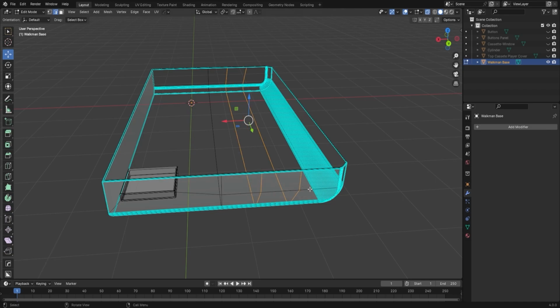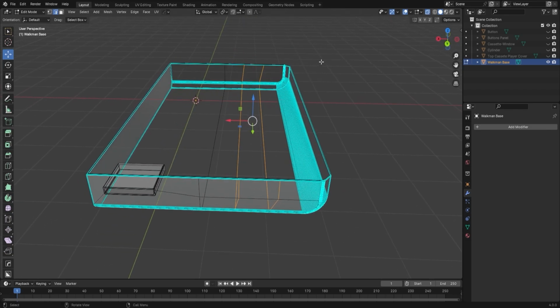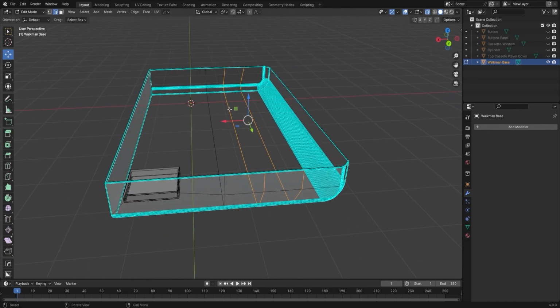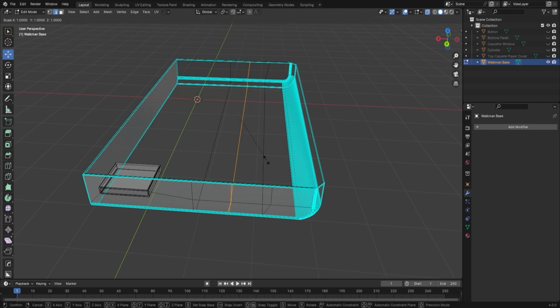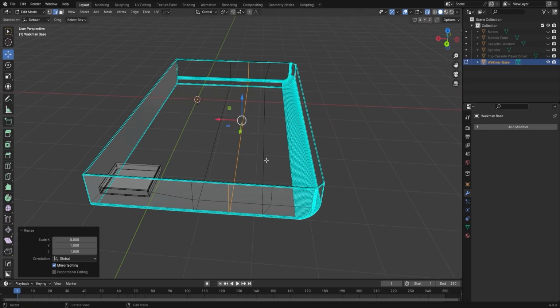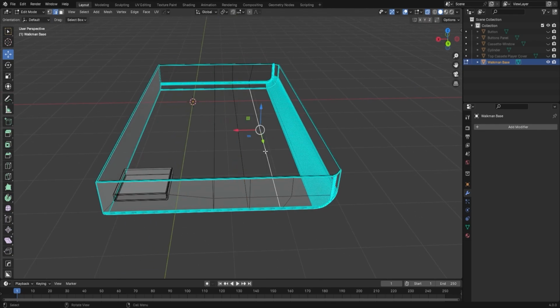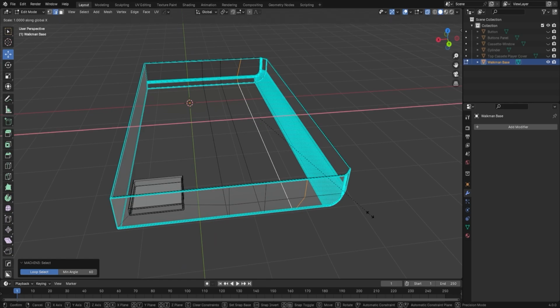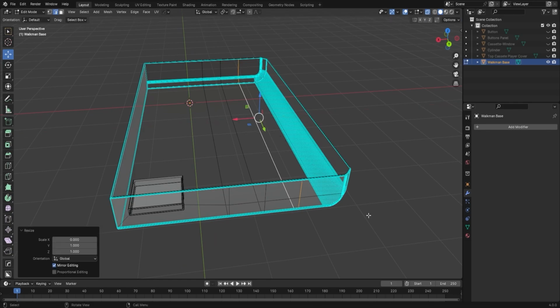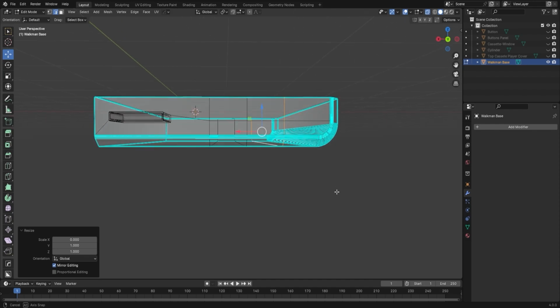Okay. Or let's undo this. Let's do one by one. First, we will select, deselect all these, press S, X, 0. And then deselect everything, and then with the help of the Alt key, I will click on one of the connected segments here, like the line here. So it will select the whole loop. So S, X, and 0. So now we have good loop cuts here.